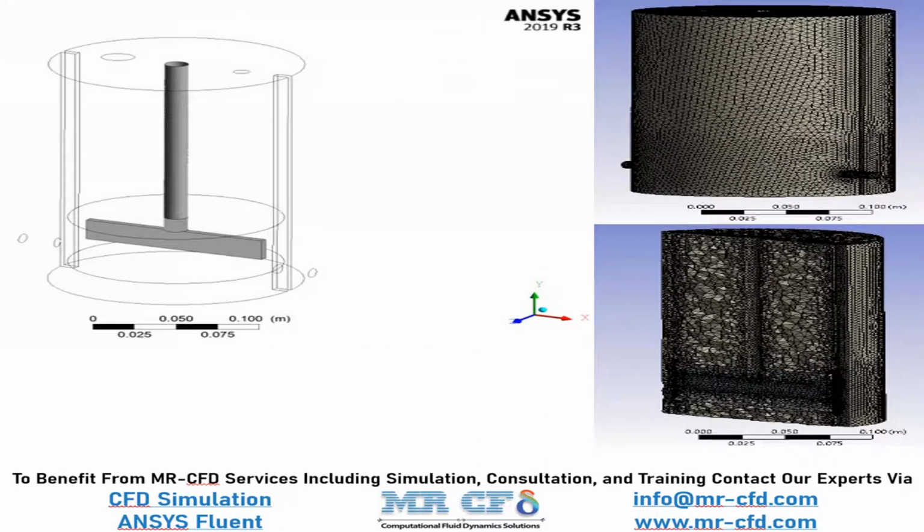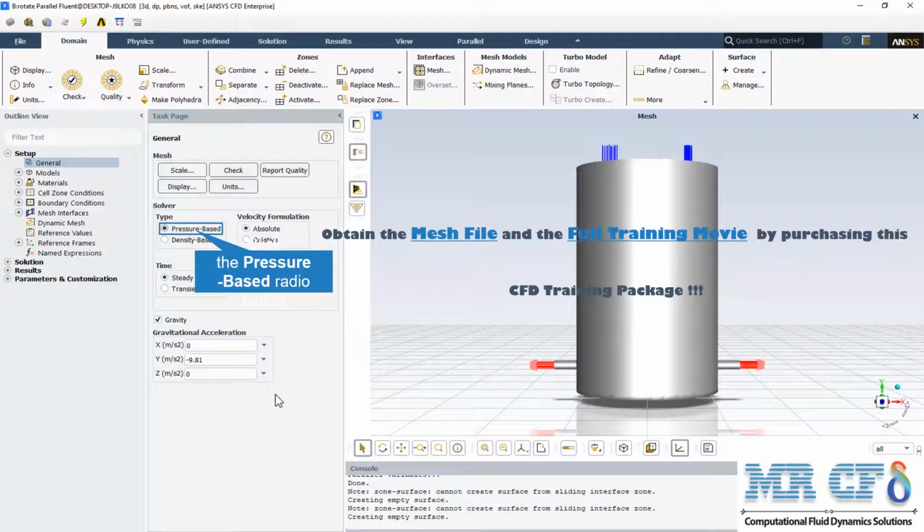The geometry of this project includes a tank and a mixer consisting of a rod and an impeller. The geometry is designed in the ANSYS design modeler and meshed by ANSYS meshing. The mesh type used for this geometry is unstructured. There are some assumptions considered in this project.